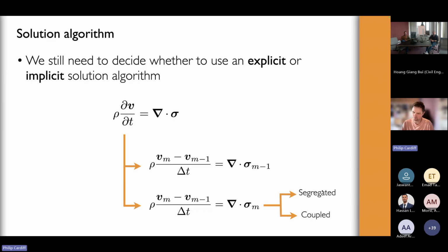The convention in OpenFOAM, due to its history for CFD, is to use these segregated methods. So you take your governing equation and you temporarily decouple it into the x direction, y, and z direction, and then you will solve these smaller, easier to solve linear systems, and you will do many iterations coupling around it. So you can do the same thing in solid mechanics. That method's not really known in the finite element community. It's not really used. Instead, coupled methods or Newton-Raphson methods are normally used.